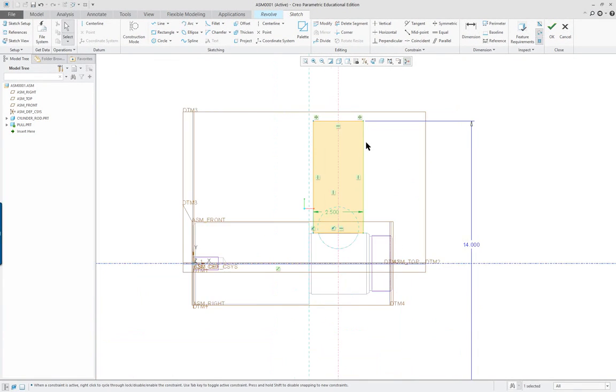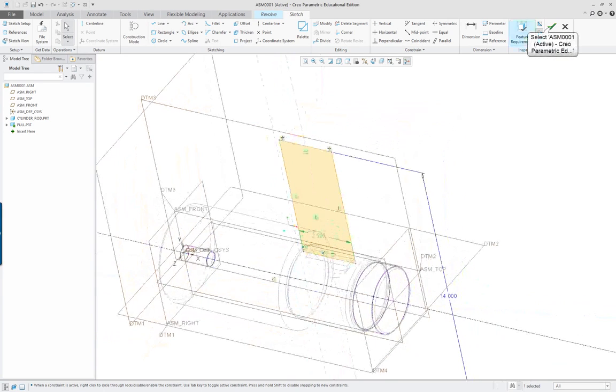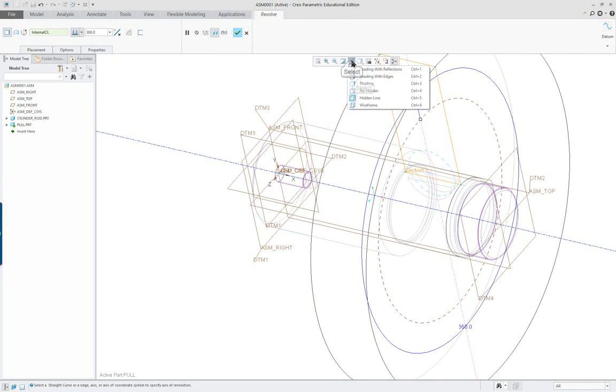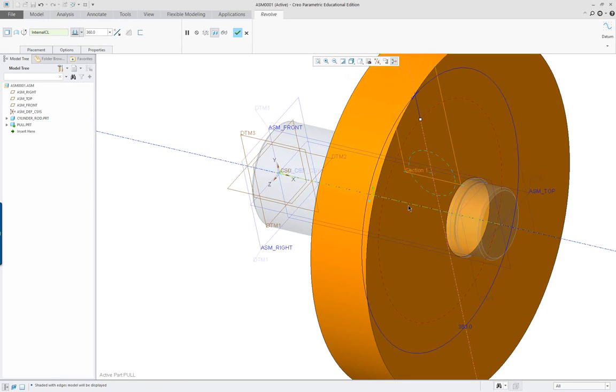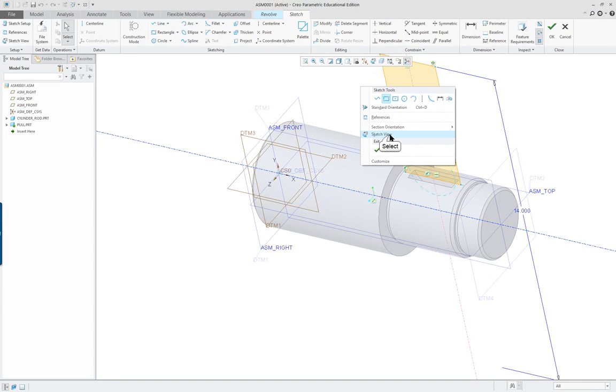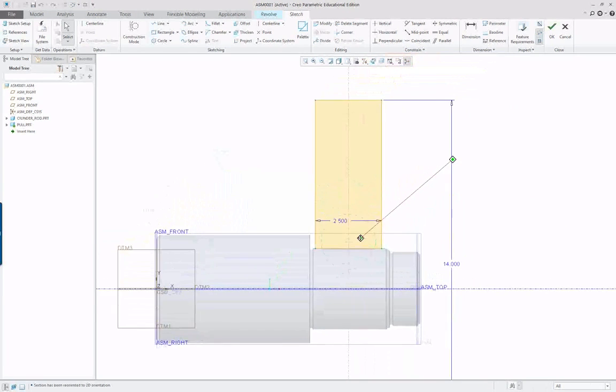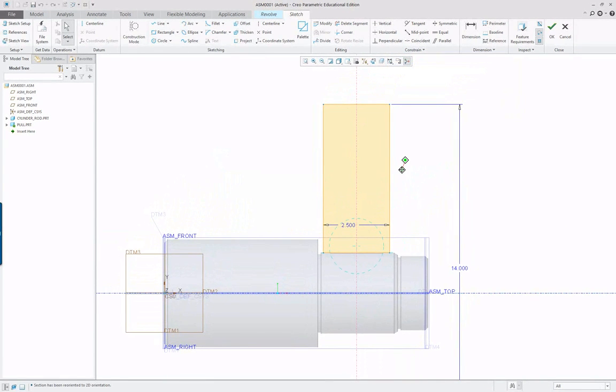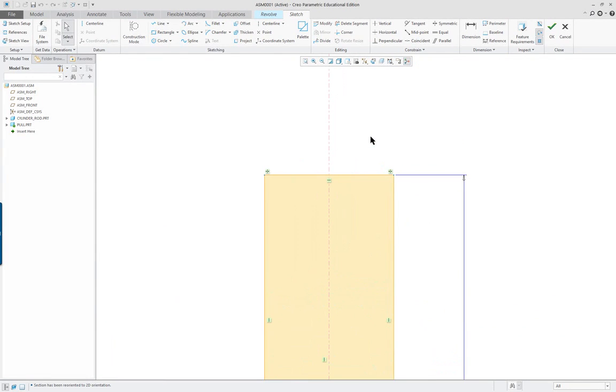All right, so this would be make a very simple, if I checked here, and let's say I put it into my shading, you'll see it's a very simple feature. But I want to go back and edit that into the sketch view. And I want to do a little bit more work here. At this end here, I'm going to put a Vcut for a belt. So right mouse button line. There's a variety of ways I can do this. I can sketch the whole thing and then make it symmetrical.